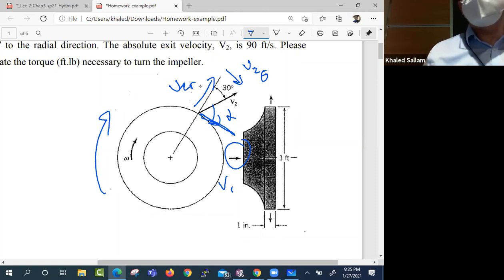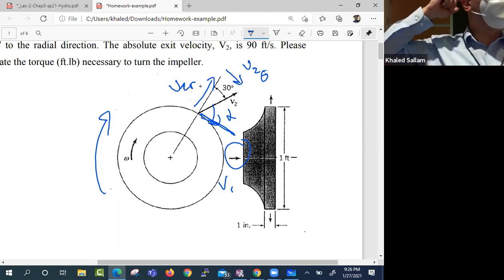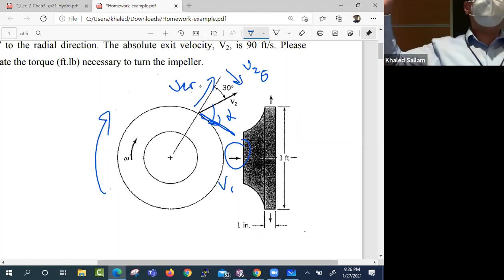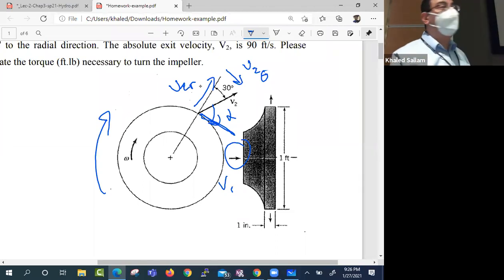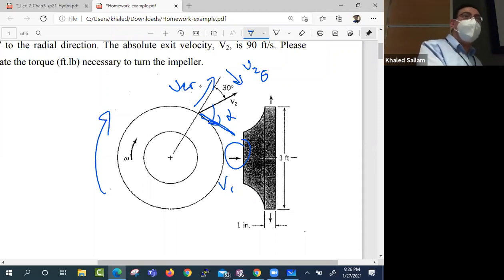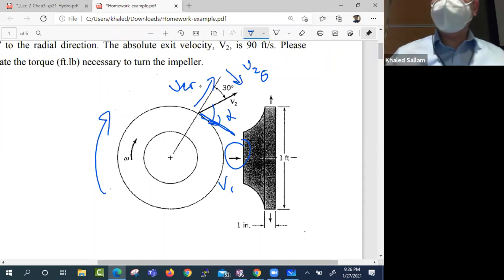And this is funny because you should think, so people build pumps to spin fluid? No, they build pumps to increase pressure. What's the job of a pump? Why would we buy a pump? Increase pressure. But again, as I kept saying all today and last week, what happens really in the impeller is just spinning. So it gave the fluid V2 theta, but then that's leaving the impeller.